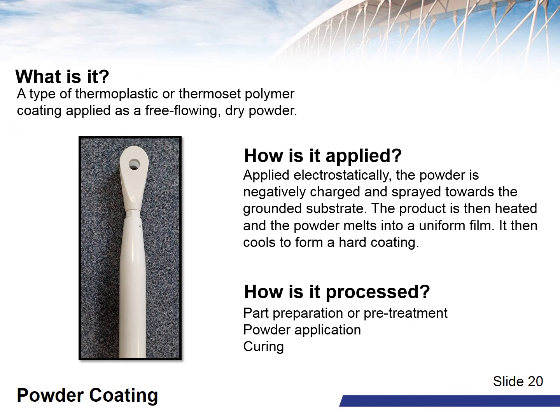Powder coating benefits. It is an environmentally friendly coating and contains no solvents and releases little or no volatile organic compounds. Very thick coatings can be achieved without runs, provides a smooth and consistent appearance, and the process time for powder coating is very short compared to a similar DFT paint system.